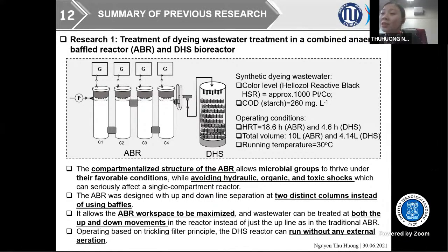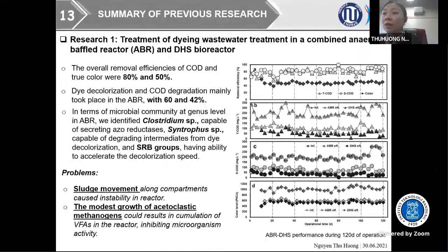This reactor can run without any external aeration. Moreover, the sponge can have both internal anaerobic and external aerobic zones that can treat the residual color after the ABR and perform a role in aerobic reduction of intermediate compounds. Here, I show some remarkable results that we already got.